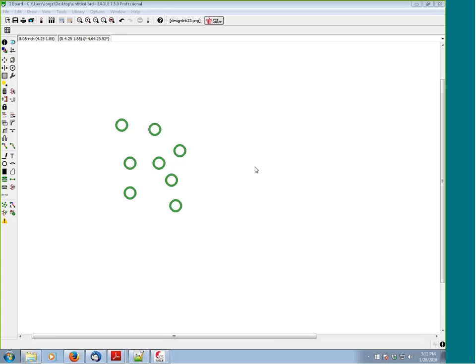The question that I have for you was regarding the star connection of the ground that you were showing in your board. I totally understand the way that you connect them at one single point to make them immune from each other. However, I don't know if you have experience with RF chips, where noise is very important to keep the RF portion safe from the noisy parts, especially if you have a DC-DC converter on the board.